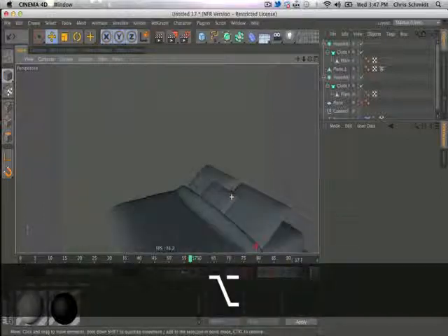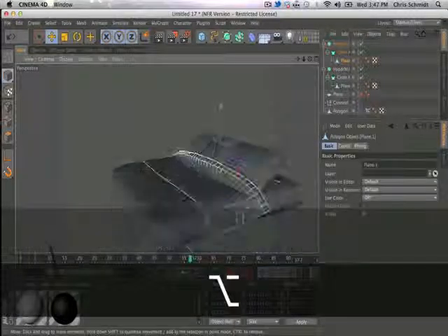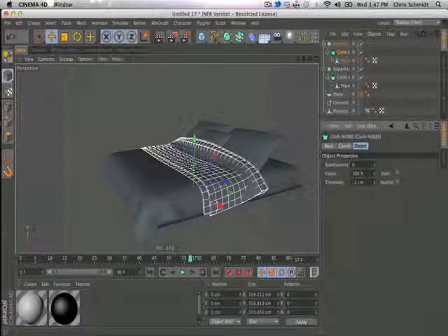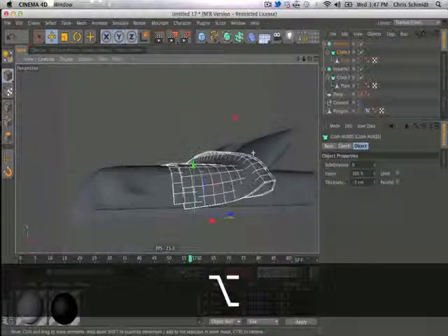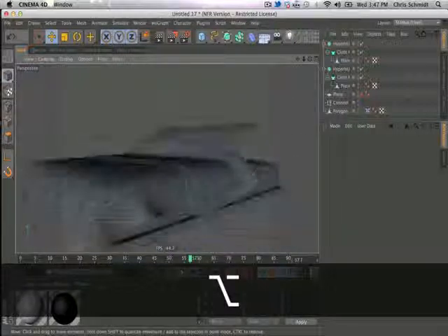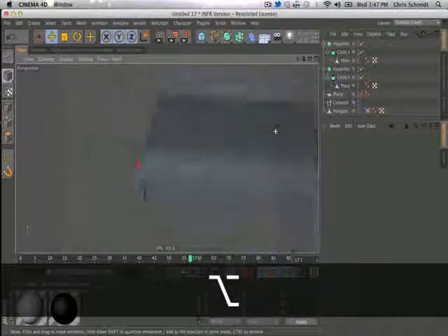Looks like it's passing through itself pretty badly. I'm going to delete that collider body. It's passing through itself pretty badly, but can that be fixed by setting this negative? So by giving this some negative thickness, it actually passes the other direction, and now it's mostly working pretty well. You see we get a little intersection right there. None on the other side.